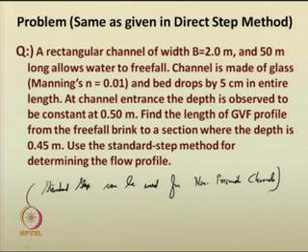You can use non-prismatic channels also if you have some ready-made problems with you already, for many rivers in India. You can use this method, direct step method, standard step method to evaluate the flow or evaluate the profile. There are many standard softwares also that use the standard step method, for example HEC-RAS and all, they use these methods for evaluating the profiles. For the demonstration purpose, we are using a prismatic channel here.